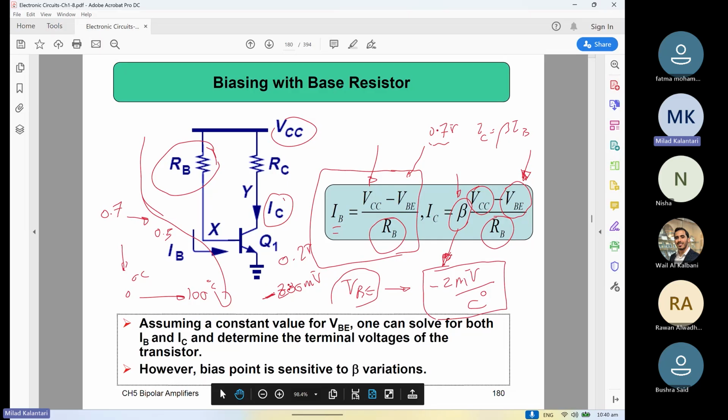But it's not only this. This beta is even more harsh than this. So overall, the transistor's current will extensively increase, right? So this bias is not good because it doesn't have any control over the temperature, basically.